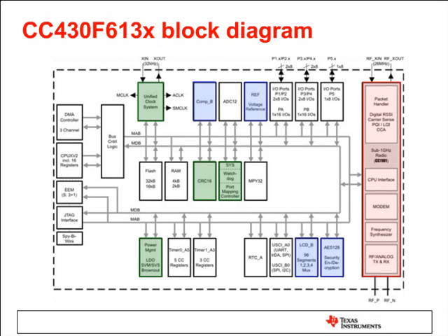We have up to 5 ports of I/O. We have an integrated reference module, which is a shared reference for all of the analog peripherals on the device that's stable over temperature. Very excited about that. ADC12, very low power, high performance ADC, a new comparator module, a port mapping feature, checksum, and a hardware multiplier. I'm going to talk a little bit about the port mapping, as well as the flash and RAM requirements. It's a little hard to read them right now.